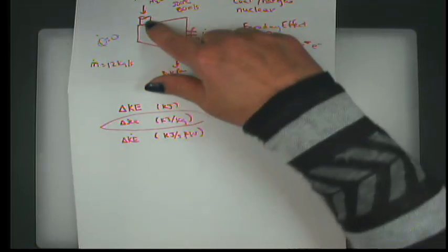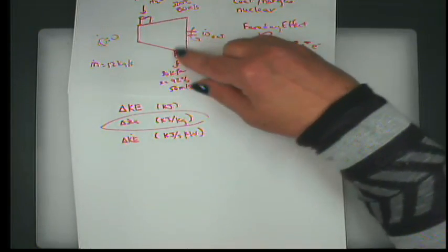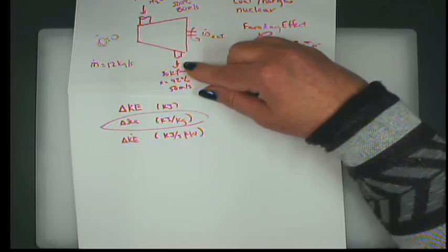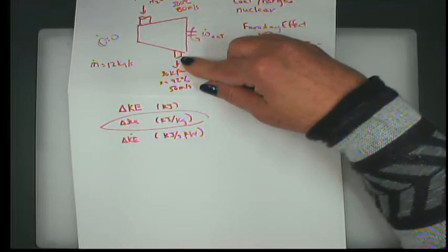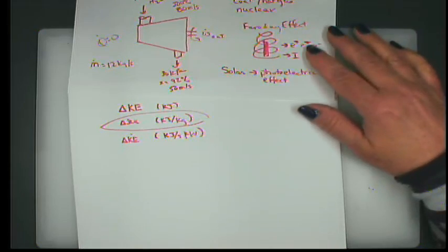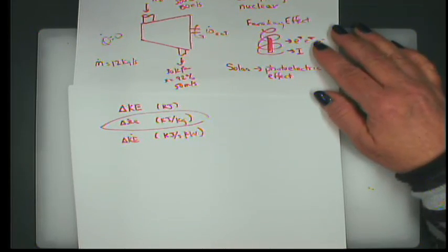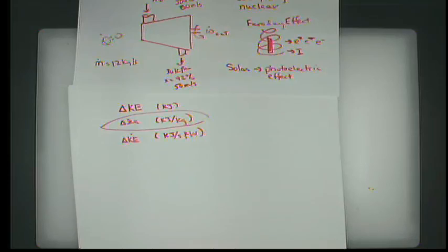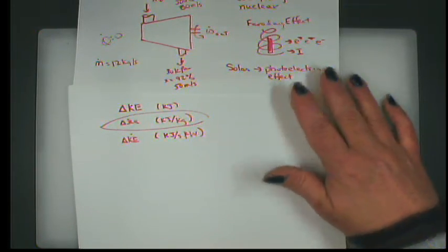The point that I'd like to make is if you go in as steam, most appliances do better in one phase or the other. If you come out as two-phase steam, you have liquid and steam, and you have a tendency to mechanically tear up equipment. So 92% is still going to behave quite a bit like just steam, so you're probably okay. But phase changes within turbines are generally tough to manage from a mechanical point of view. It's not going to make any difference on a piece of paper, but if you try to do it in real life, it's going to be a problem.